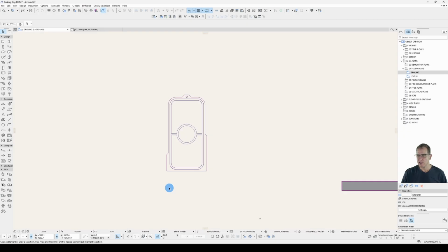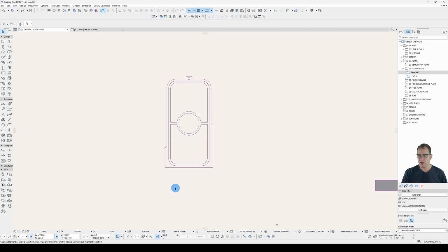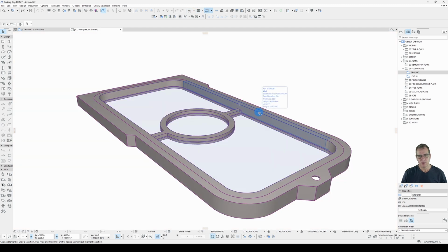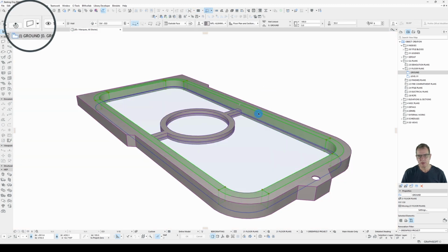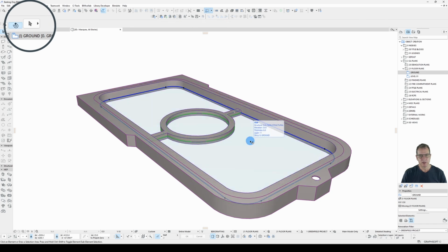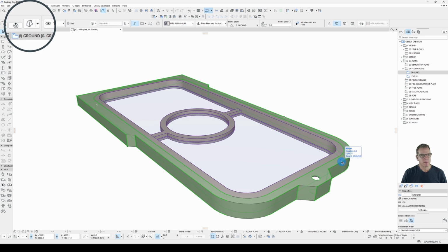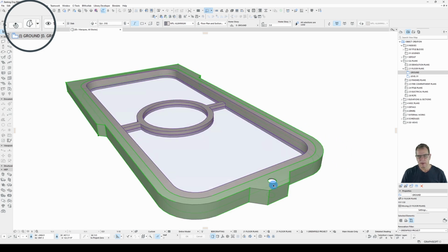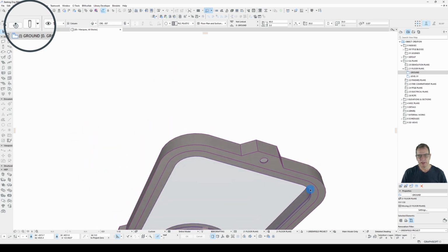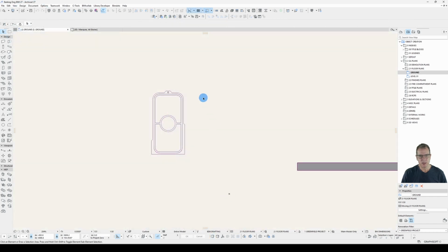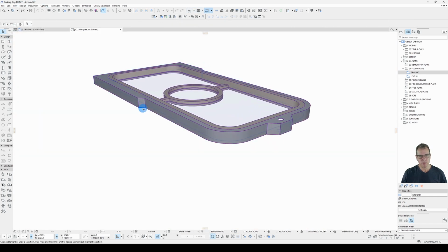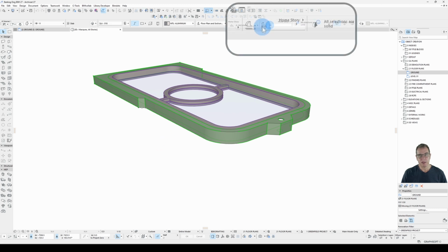With the save as method, you model your door using native Archicad elements. So I've used a series of walls for the leaf and the glazing bars, a slab for the glazing itself, a morph for the door frame, and a column for the overhead indicator light. Now there's no need for these to be modeled on the X and Y origin, but you do need to model them on the Z0.